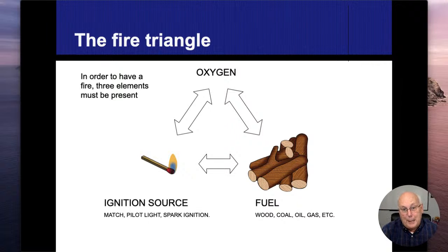Usually when we don't get a complete burn, and we usually don't, we're going to start getting some byproducts that come out of there. So carbon monoxide is going to be our number one byproduct that we're going to be measuring for, or we may choose to measure for. We do put carbon monoxide alarms inside of our residential buildings. And I think that's important enough to say that in the state of Illinois here, we do have a carbon monoxide law. So we should be having a carbon monoxide alarm within 15 feet of every bedroom.